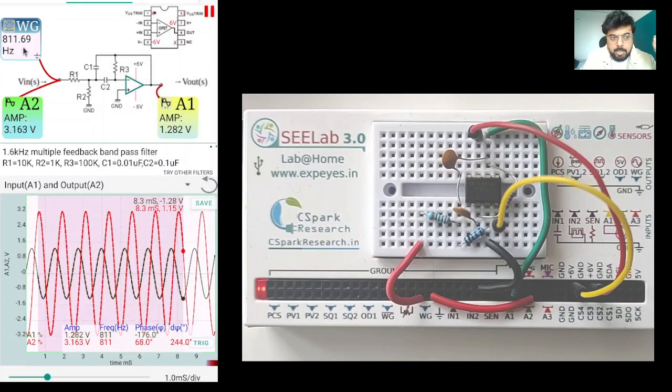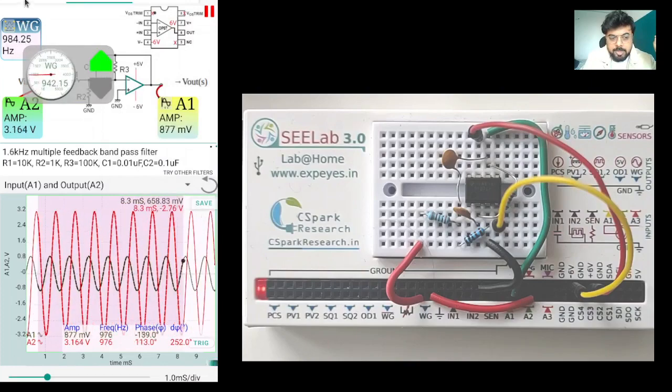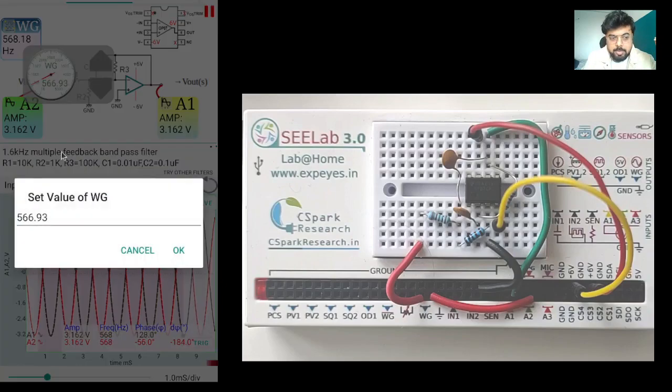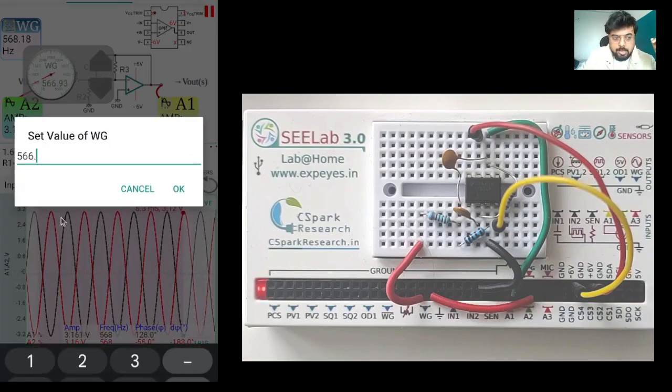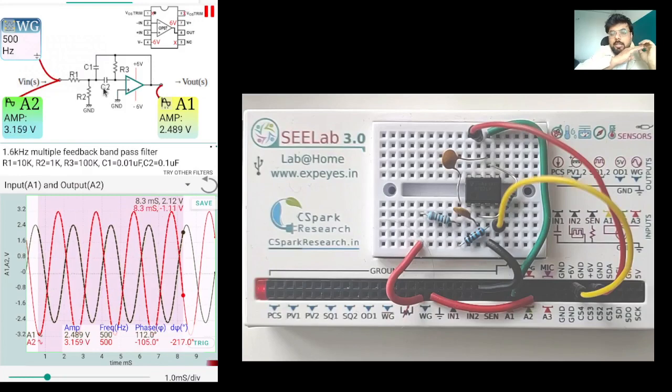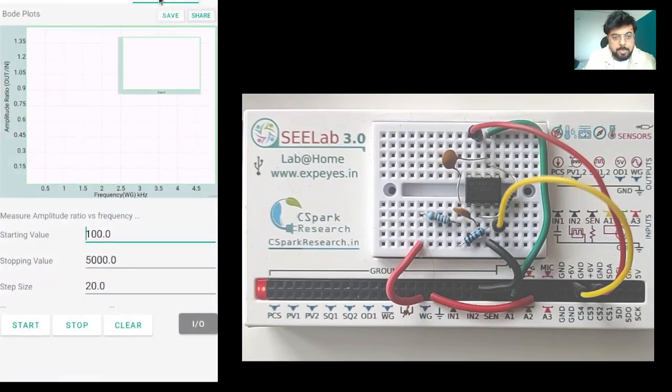Okay. So this is a sort of interactive mode where you can manually set different frequencies. If you want to set a precise frequency, you can tap on this and say, I want exactly, I don't know, 500 Hertz. And it'll tell you, okay, fine, we've set 500 Hertz. But if you want to get the filter characteristics graph and also look at the phase relationship as you sweep different frequencies, you would need to go to the record data tab. So here I have record data next to this.